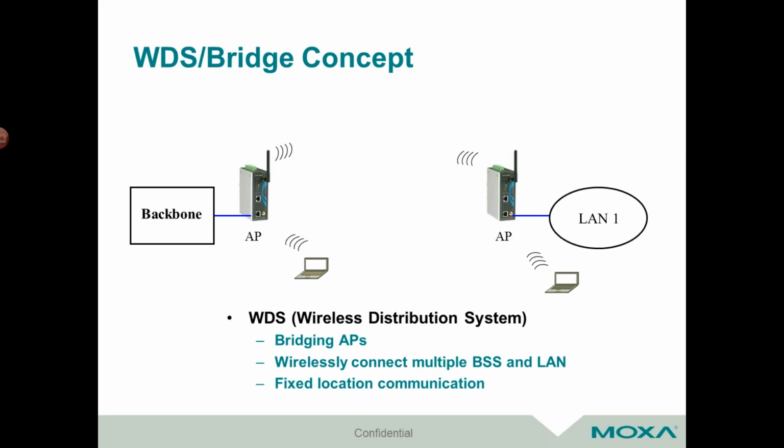link. But this type of topology is very, very useful when you're trying to bridge longer distances or bridge two separate facilities together. So say, for example, you have your control room, and then across, maybe an open field, you've got, I don't know, a water tank that you're trying to monitor with multiple sensors. So you can wire all those up into a device that communicates to a wireless device that will communicate back to your control center, and you have that dedicated link between the two of them.